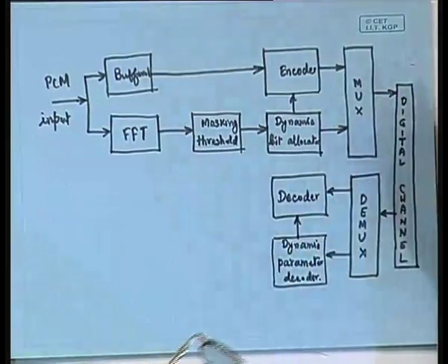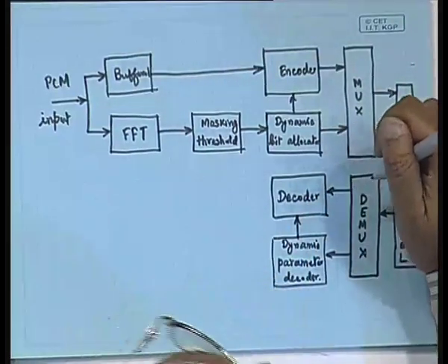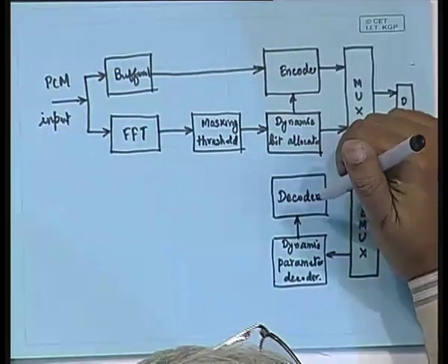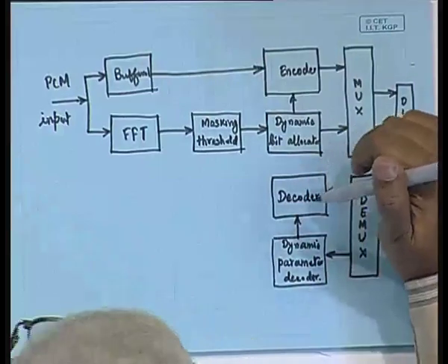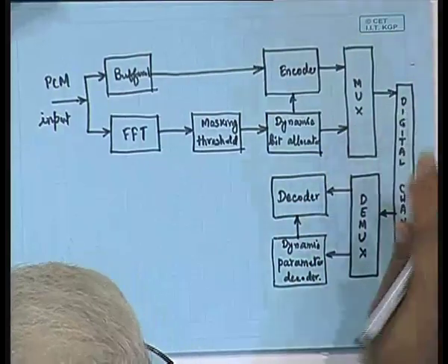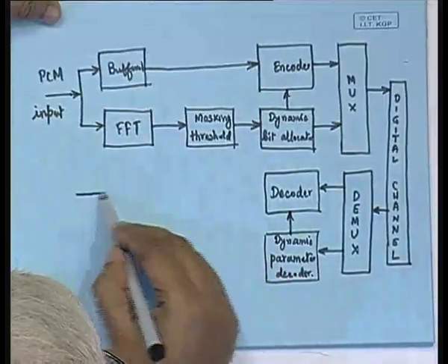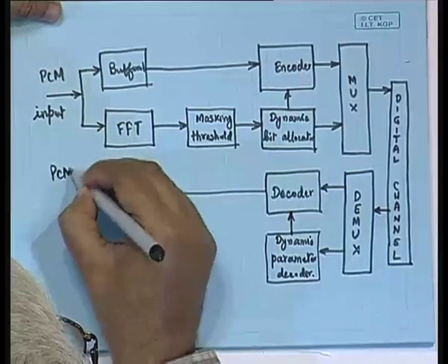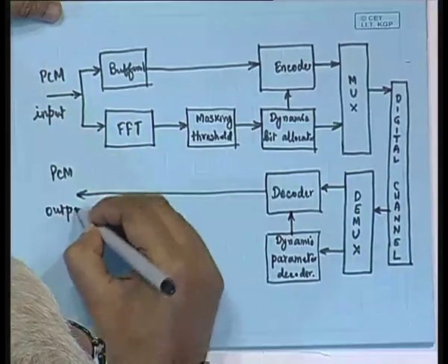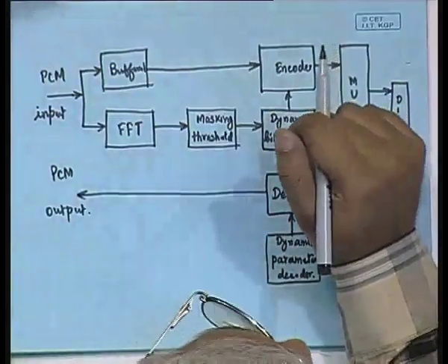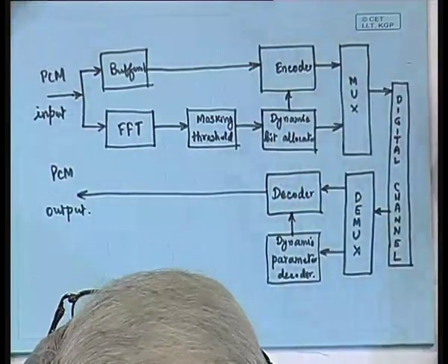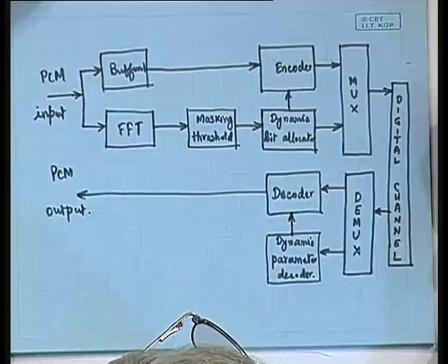and after extracting the bit allocation parameters, it has to notify the decoder accordingly, because based on this the decoder will extract the samples. The actual extracted samples will be obtained, and the decoder output will be the PCM output, which will be used for the reconstruction of the signal. So, this is where we expect the PCM output to be exactly the same as the input, provided the model is absolutely lossless.